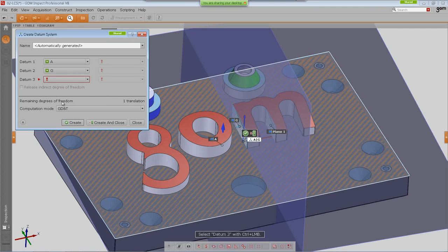I've mentioned this before on the local coordinate system. There the default behavior is the geometry. So you can either choose whether you want to go to geometry or to GD&T mathematics on both sides, on local coordinate systems and on datum systems. But the default behavior is different for those two elements. This is important to know if you want to do such things as I've shown you before.